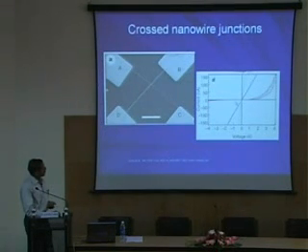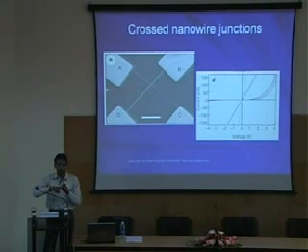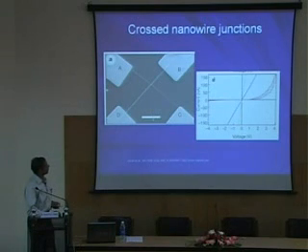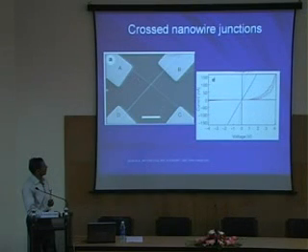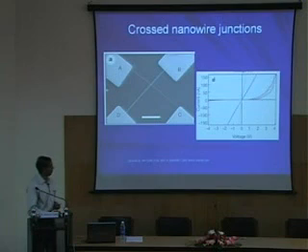These are some of the properties of this crossed wire array. If these nanowires touch each other, there is a p-n junction formed. During the growth of these nanowires, you can dope them very precisely, either to be p-type or n-type. And these are the characteristics of this nanowire made of indium phosphide. That is why you see that they start conducting at a larger forward voltage here. Between these two nodes, you have a linear characteristic. Between these two nodes, you have a linear characteristic. But when you check between these two nodes, you will get a p-n junction characteristic. A p-n junction is a building block for any electronic device.